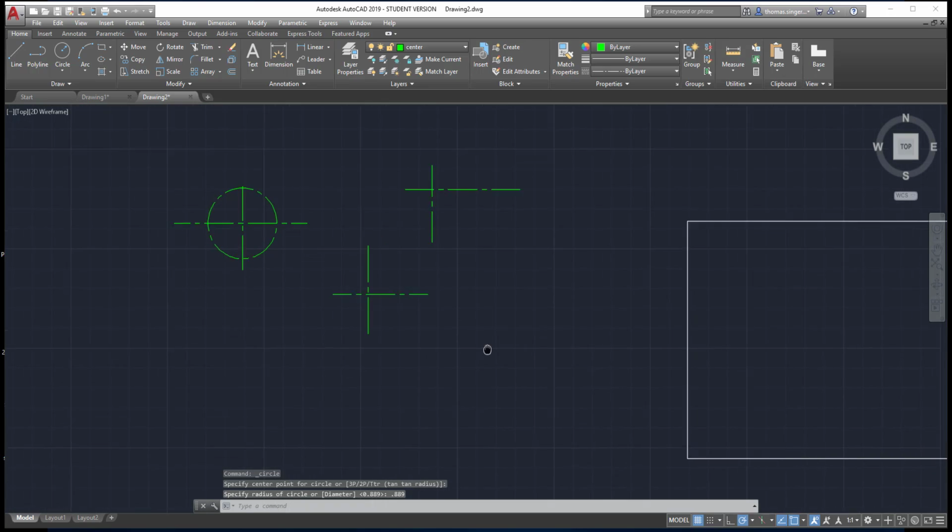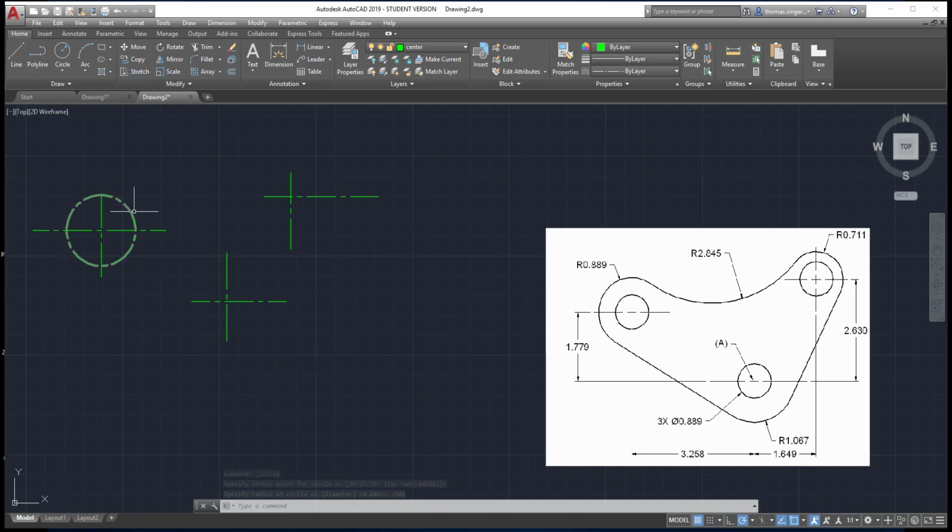And I've just created the circle, and that circle, unfortunately, is done on the wrong layer. So now I've got to change that layer from the centerline layer to an object layer. So I'm going to select it and put that grip tool back on it and come up here to the layers and switch it over to the object layer. And again, as we've talked before, we never want to draw on the 0 layer. We always want to create separate layers for each of our objects and each of our entity styles. And so now that we've got the object correctly positioned on the layer, we need to go back and change our center layer back to the object layer and make that the current working layer itself.